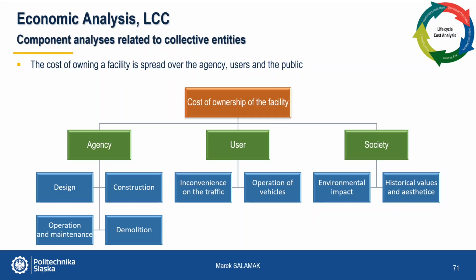Then we have the user. It is each beneficiary of the investment which bears the costs of using the resulting object, building or bridge. These may be the costs of vehicle operation and losses related to traffic obstructions or speed limitations caused by deterioration of the facility's technical condition, or detours during the renovation of the structure.